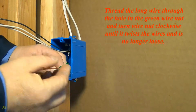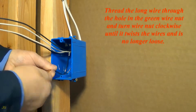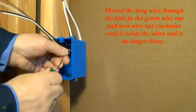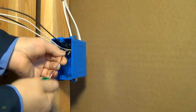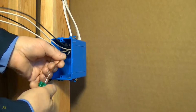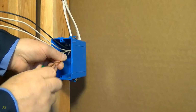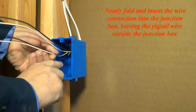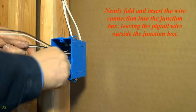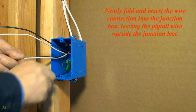Thread the long wire through the hole in the green wire nut and turn the wire nut clockwise until it twists the wires and is no longer loose. Neatly fold and insert the wire connection into the junction box, leaving the pigtail wire outside the junction box.